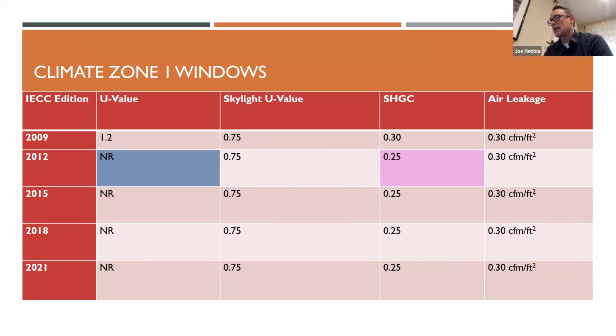It should be on the NFRC label in any home that's built in a jurisdiction that's adopted the IECC. It's not always on the label, so it's important to make sure that air tightness target is there. And that's the way the code controls convective heat across that window assembly, air leakage actually through the window itself.